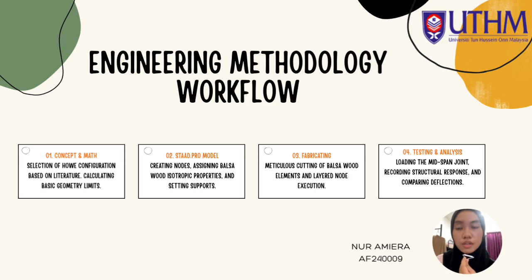Next, I will explain the engineering methodology that we use in our project. First, we select the Howe truss configuration based on information from previous studies and engineering references. We also calculate the basic geometry, including the span length, panel dimension, and member arrangement to ensure the design meets the project requirement.